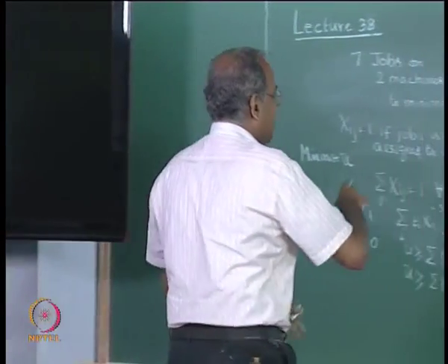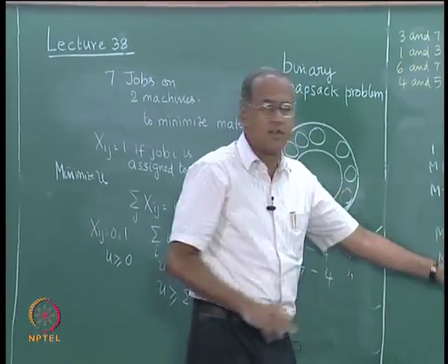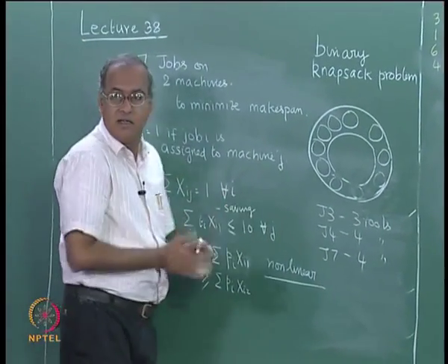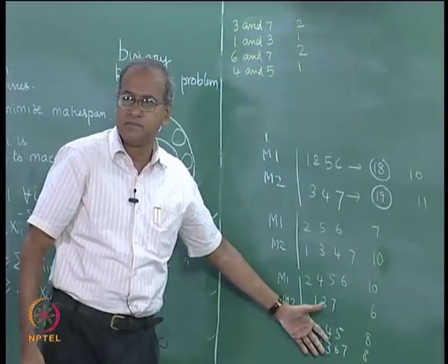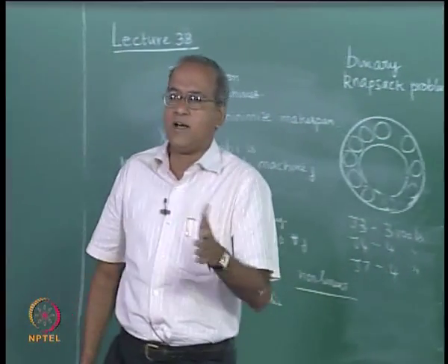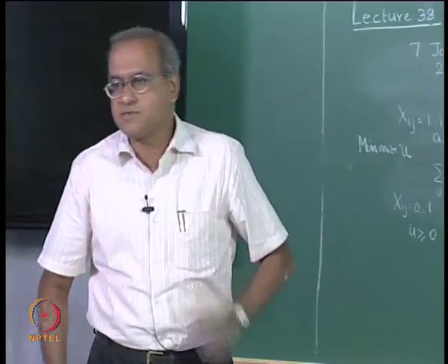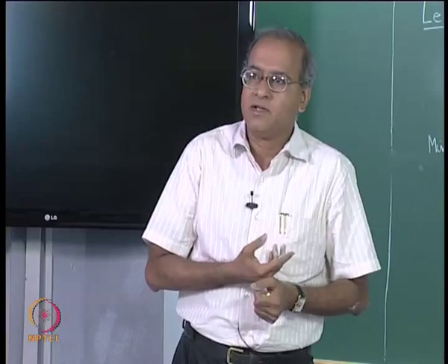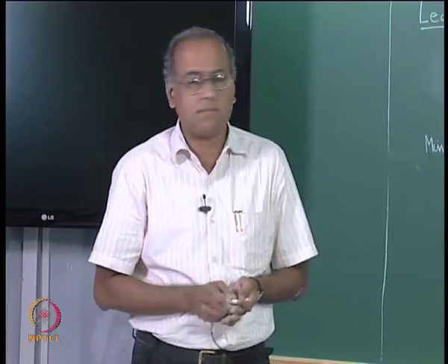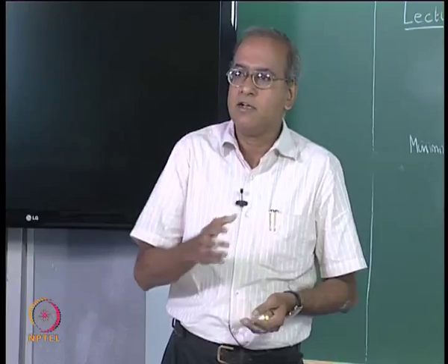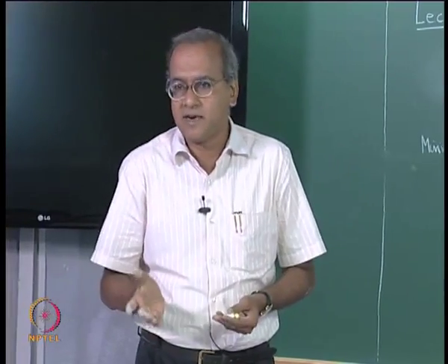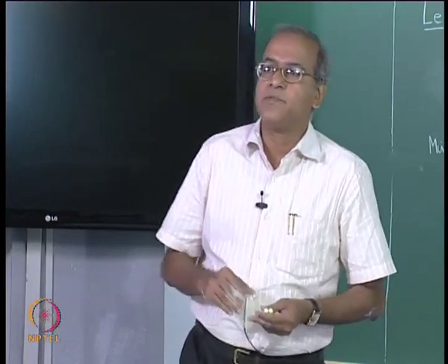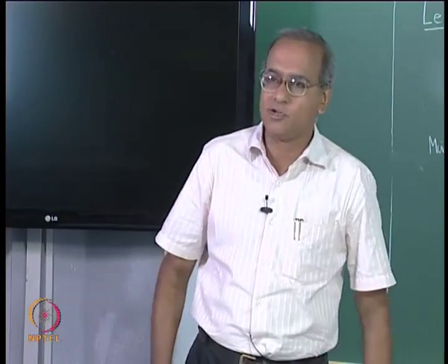So non-linearity will create a lot of issues when we do this, particularly either when we try and solve this here or we try and solve this here. It is not impossible to do that, but non-linearity will bring in issues. Now the knapsack problem has to be modified. So there is a branch and bound algorithm which has been published by Barada and Steck, which takes into account this non-linearity, and then it develops a branch and bound algorithm to do load balancing, considering tool slot saving also.